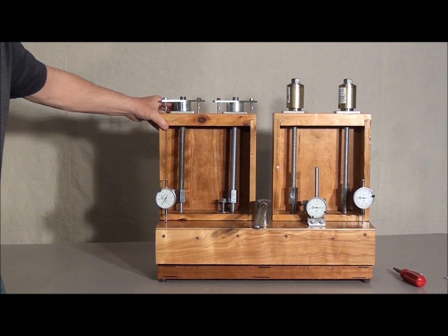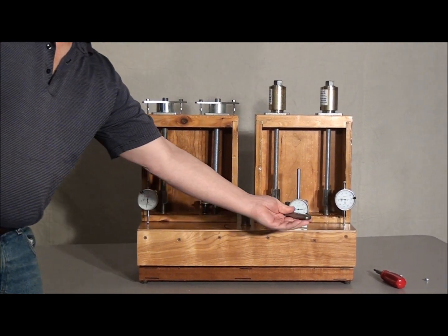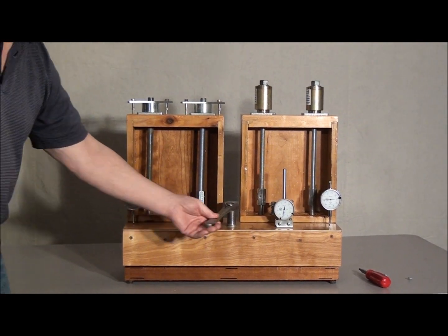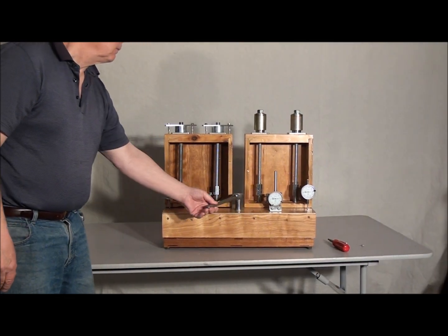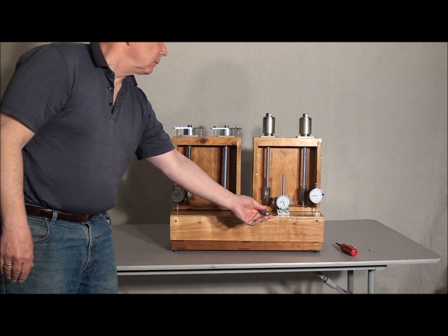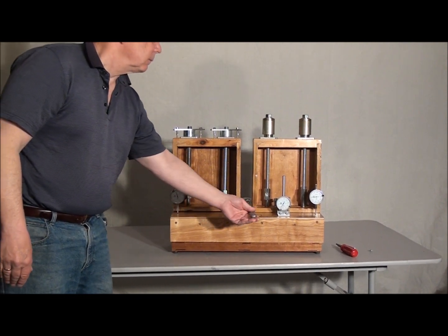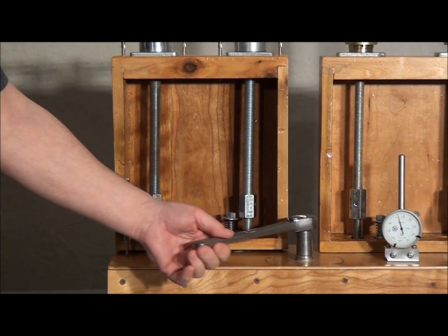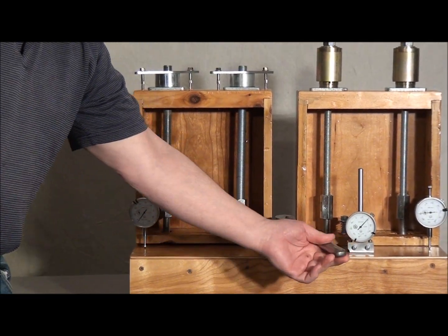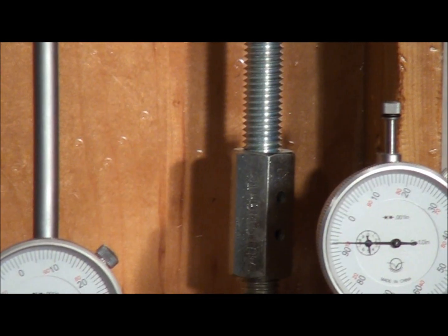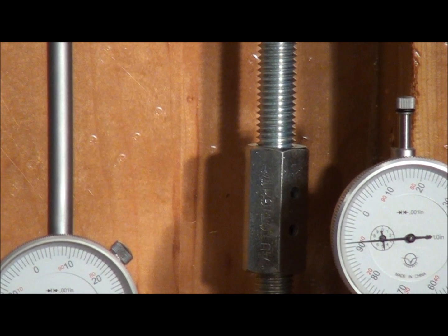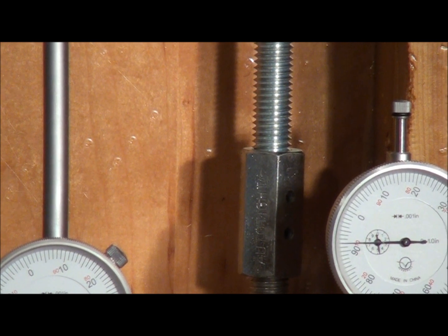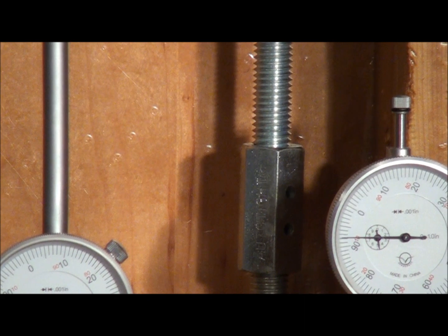Shrinking the floor gives us the same results. Very little deflection on the screw type TUD. The ratchet side shows the same amount, 50 times as much as the screw type TUD. It doesn't matter how much you shrink the floor, you will still have the same reaction. Very little movement on the screw type side and a great deal of movement on the ratchet side.